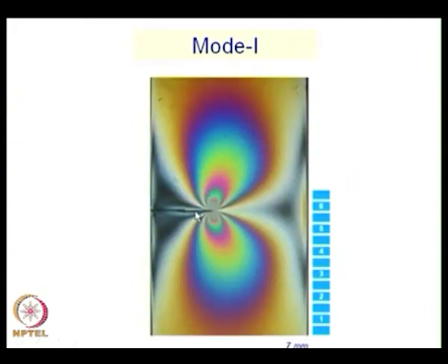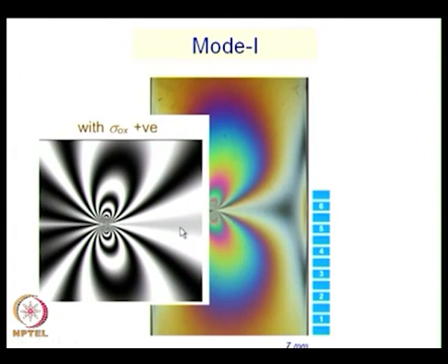The moment we go to mode 1, when I have a short crack like this, I have my fringes tilted, and they are tilted forward in this case. If you look very carefully, I have the tilt like this. As you go close to the crack tip, they become straight. So, by raising this question, I appreciate that you have observed this phenomenon. How can we interpret it?